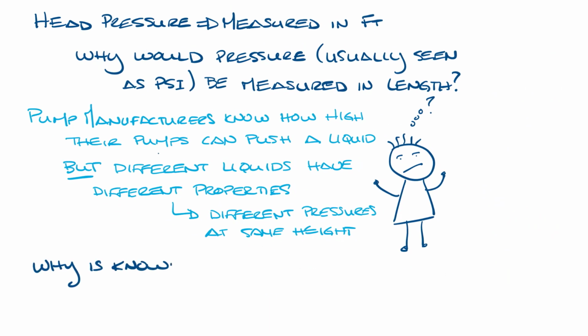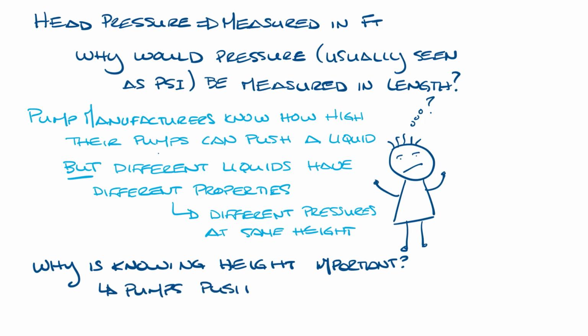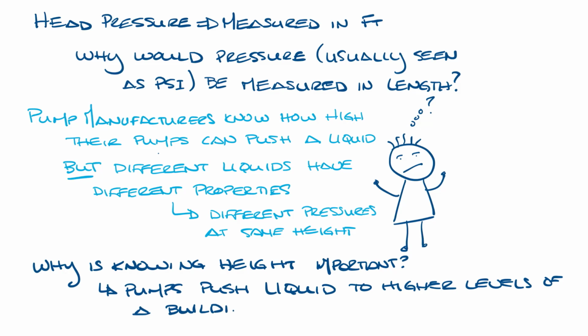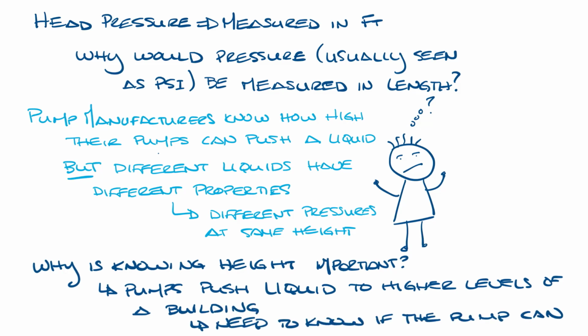So why is knowing the height the pump can push the liquid important? Well, pumps are usually pushing liquid, let's just call it water from here on out, to a higher level in the building. So you need to know that you have enough head pressure to get the water there. Okay, let's scoot this over.